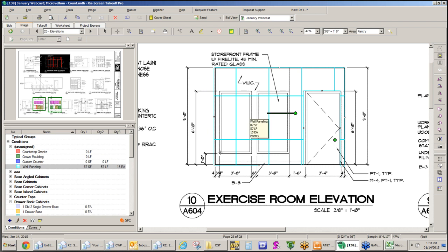I want to back this out, is what I meant to do previously, and I don't know exactly why I did something so silly. So now you'll notice that it no longer put that wall paneling inside of the window area, and so now it's changed the calculation for this. The actual number of tiles are what we calculated, but it's calculating the appropriate square foot and the lineal foot that we have of these as well. Maybe there's going to be edge banding along all of the panels, and we want to know how many panels, and we want to know how much square footage. And so there's a number of things that you can do to make some really good calculations.